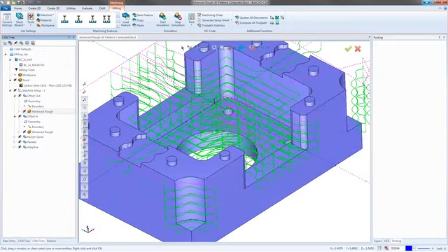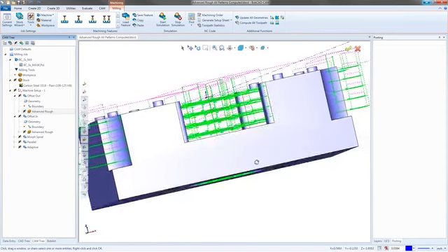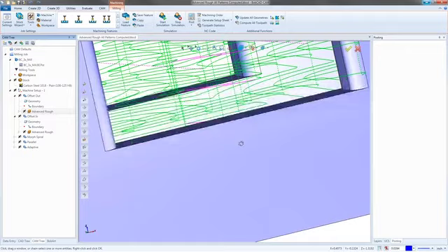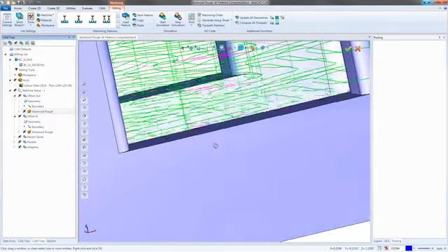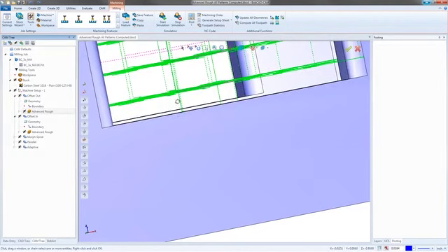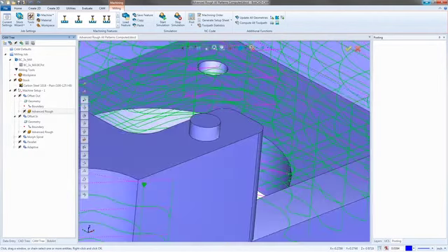But you'll notice, since I didn't turn on the machine flatlands, we didn't get a nice cleanup toolpath here all the way around. Decent looking there, and I'm sure these will be fine. But that's only if the toolpath naturally ends right at that point. So you'll see right there, there's no toolpath on that ledge. So this toolpath is going to be cut to up to this point right here. So we do have some material still to clean up.